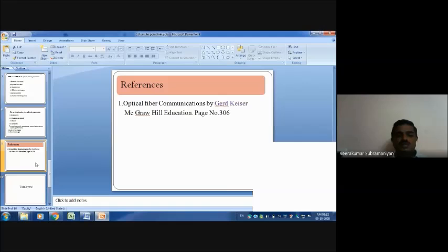On the transmitter side, receiver side, and the channel side, I mean the fiber optic cable. On the transmitter side, wavelength, source, that kind of things. For fiber, core radius, mode field diameter, that kind of things. For the receiver part, sensitivity, responsivity, speed, those kind of things have to be considered.